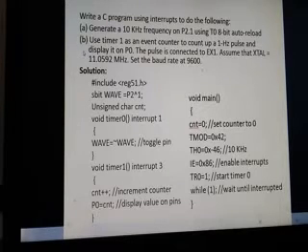One, timer is used as a timer. Second case, timer is used as a counter. So two tasks over here, and two timers are used simultaneously. So see over here, include the header file. P2.1 square wave has to be generated, so P2.1 value is given to a variable named wave.